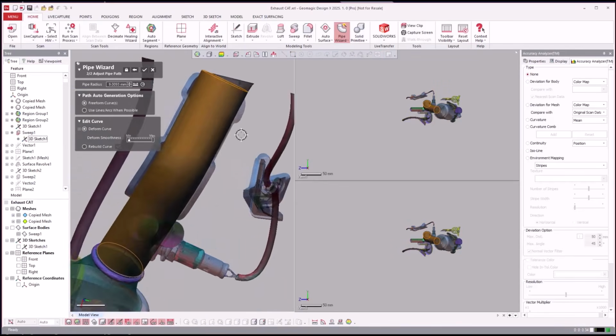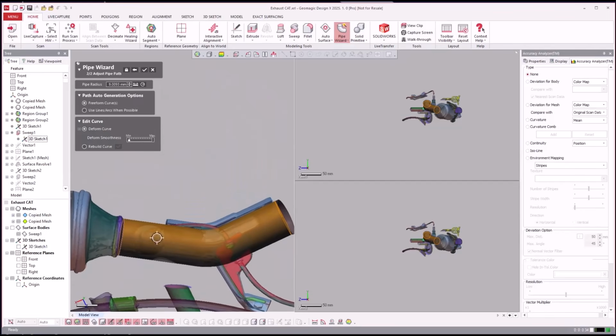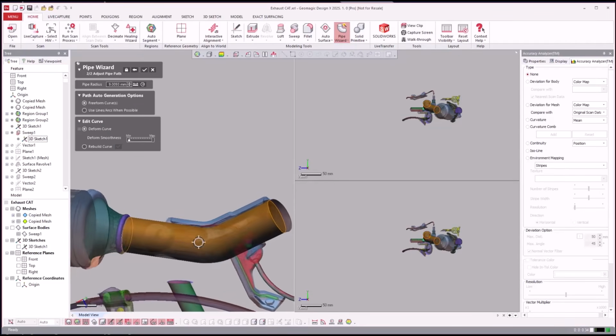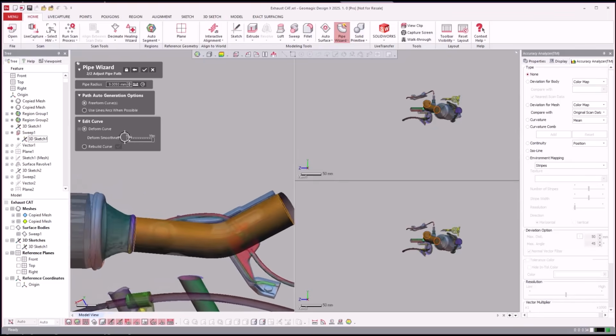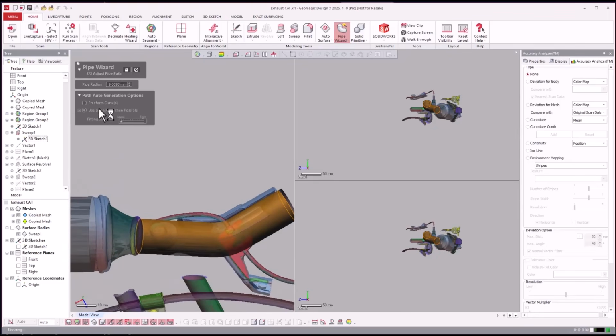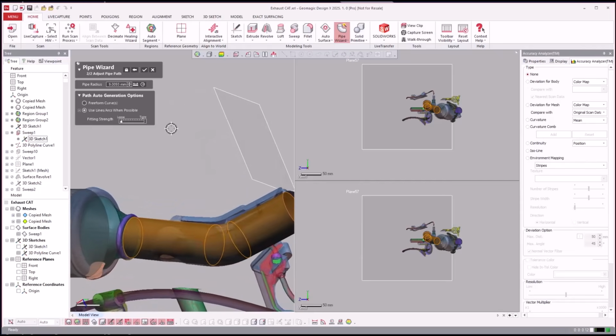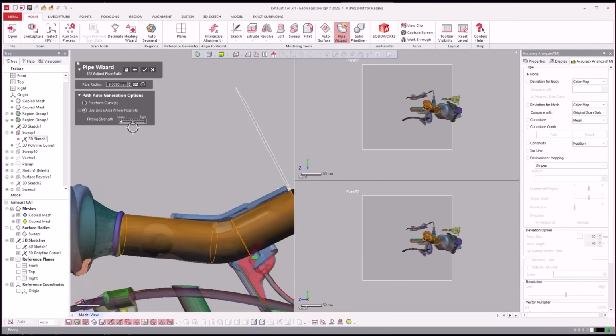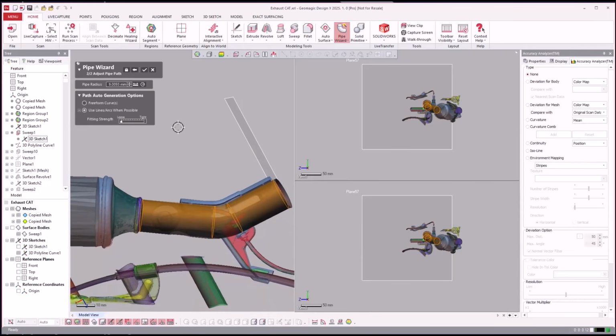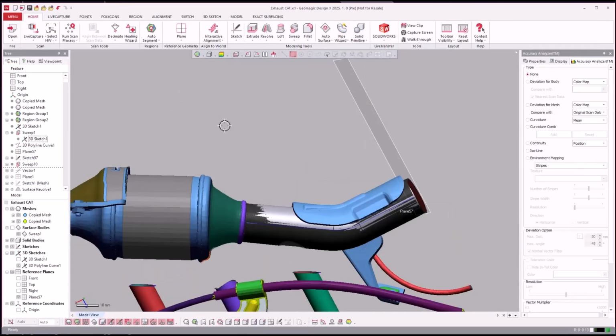And this tool is just so cool how fast it works. You see there, it goes and it creates a center line and draws it as a spline and then a profile and then gives you the preview. And you can tell it, hey, calculate this as a line arc instead of a spline. And I'm just going to do that with mine. And you can even override and say, hey, this has to be a 9mm pipe radius, and then hit OK. So I just made it.